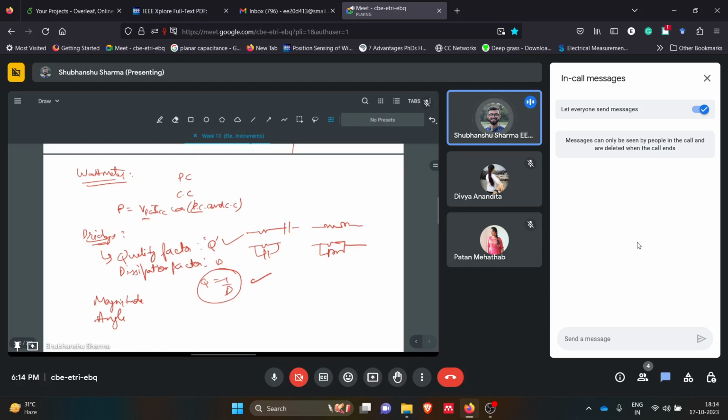One more thing to keep in mind, whenever you have this magnitude-based relation: let's say there is Z1, Z2, Z3, Z4, and across this we have to measure A and B. The normal balance condition will be Z1 by Z3 equals Z2 by Z4.